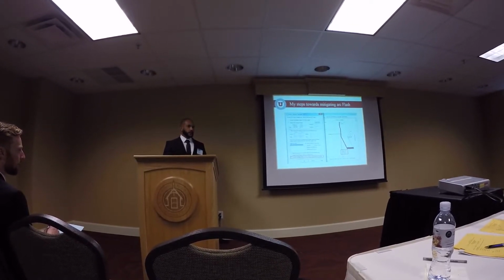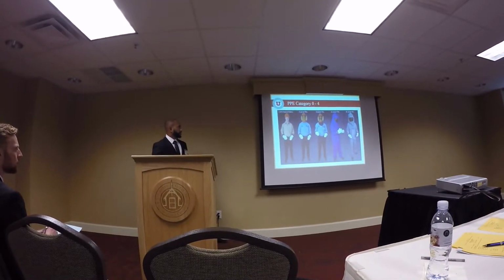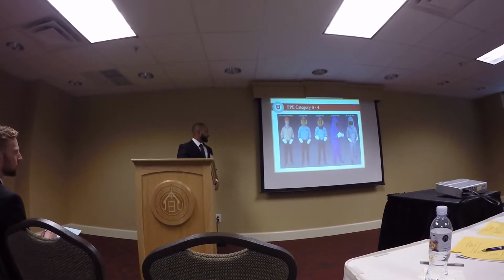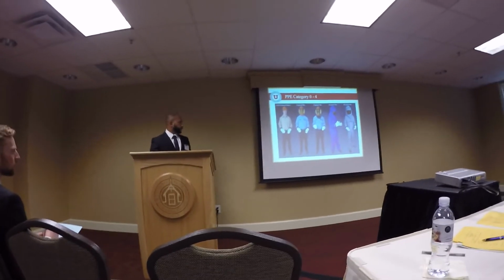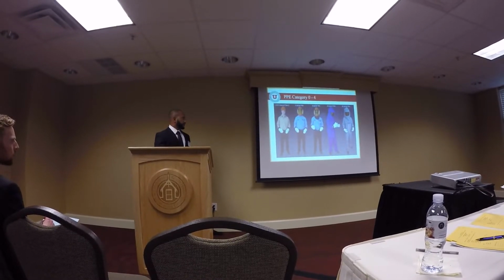This gives me an indication of the category level of the risk hazard. One may ask, what is a category level? The United States has graded PPE, personal protective equipment, from 0 to 4. Category 0 is FR clothing, a hard hat, a pair of goggles, steel toe boots and safety gloves. You can easily perform the tasks you need.